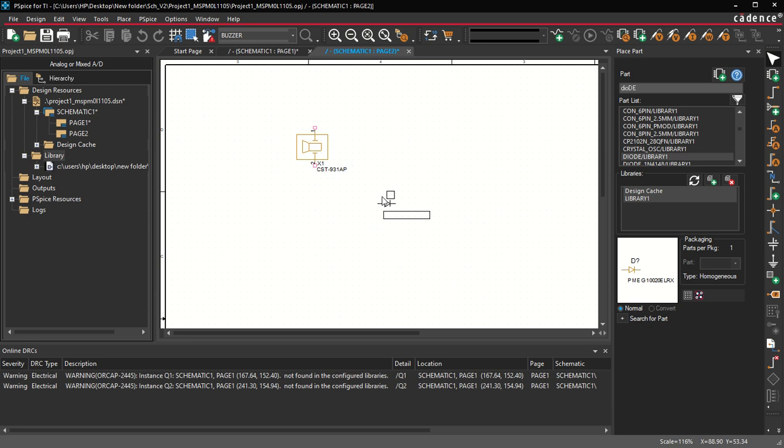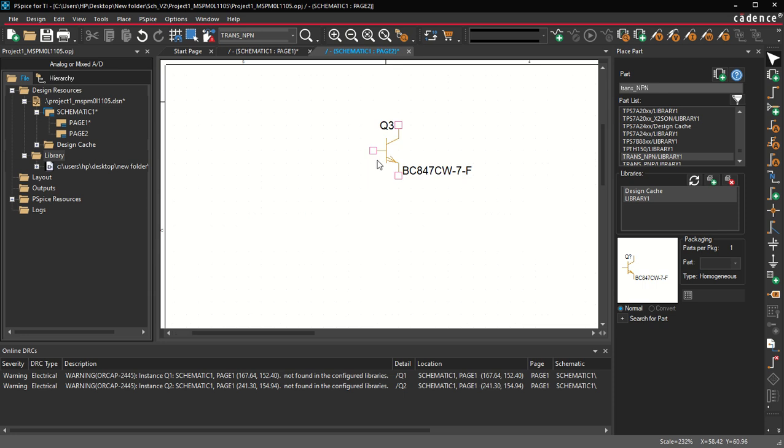So let us put one diode, and we need one transistor. If you want you can utilize a MOSFET as well, but right now I'll just give you an example with a transistor. So let me just put a transistor. To drive this transistor we need the PWM signal, that's the thing that we are going to do. However, before that we can have a voltage division so that we can supply base to emitter, right? So we have to give a base emitter voltage source.